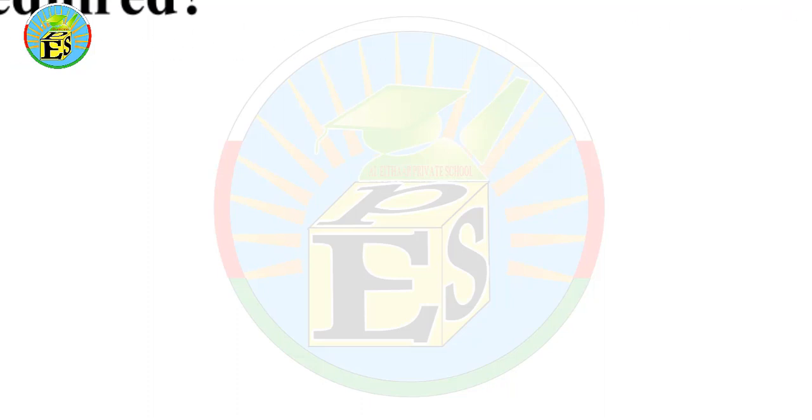Now we have a temperature rise, so it gains energy. We need the energy required to raise the temperature of the aluminum mass from 25 to 55. By using the specific heat capacity of aluminum, we can calculate the energy.